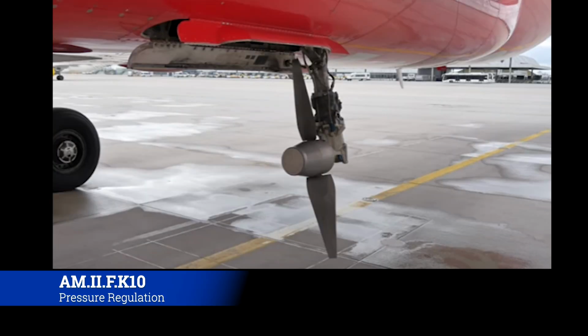Okay, finally, here is one of my favorite things on all heavy commercial aircraft: the RAT. Now, the RAT stands for the Ram Air Turbine. What this does is that in case of an electric or hydraulics failure, you'll see the RAT get deployed, and it'll start to spin that little turbine, and that little turbine then adds hydraulic pressure to keep everything going. It also works like a generator and helps keep the lights on as you precautionary land wherever you can.